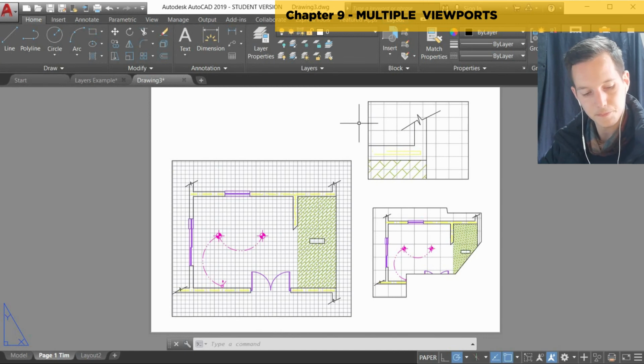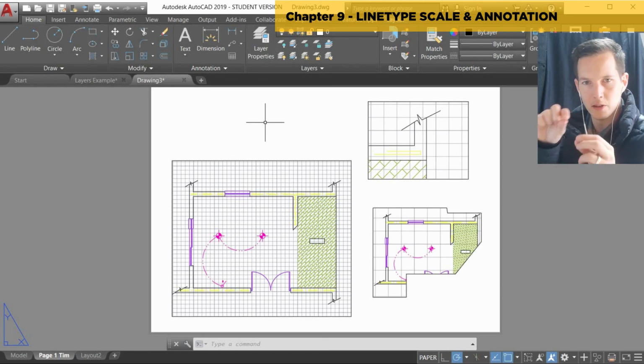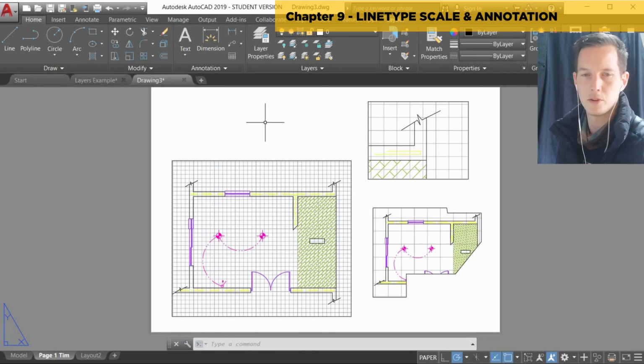It's quite versatile. So there are different ways and approaches to annotating a drawing. When I say annotate, I mean basically add things like dimensions, multi-leaders, which are like little labels, and text, okay? All the drawing and page information that can't be expressed with the actual lines and drawings of the things, okay? Whenever you want to label something, for example, when you see a plan and you see a piece of text that says this is the bedroom, whatever, that text is created separately to geometry and the lines that make up the walls and floors and furniture, all the other things you see in the plan.